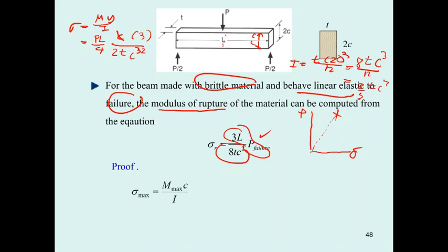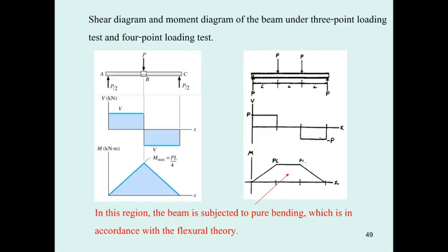You can prove it easily, and many times in the examination I ask you to prove this step by step to get the equation that we can use to determine the modulus of rupture of the brittle material. It's very useful to determine the tensile strength of the brittle material.